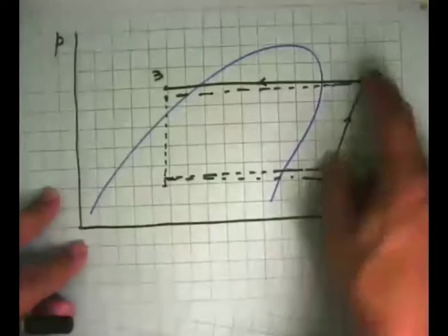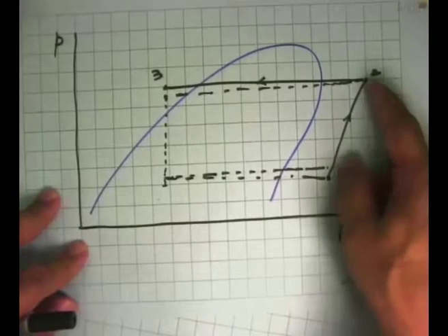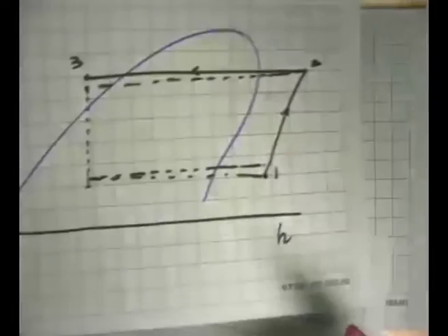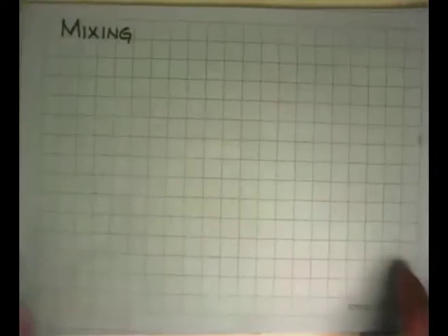Ducts are nothing but air flowing through them, and the same theory applies to duct flows. This is important for pressure drop, and all these pressure drops have to be ultimately taken up by the work input device, which in this case is the compressor. If it is a water system, then all the pressure drop in the pipe has to be taken care of by adequate pressure build-up in the pumps. So your pump design, your compressor design, the fan design, they depend on the design of the pipes and also pressure drops which will take place within the cooling coils or some heating coils or some other tubes. So that's where this is important.